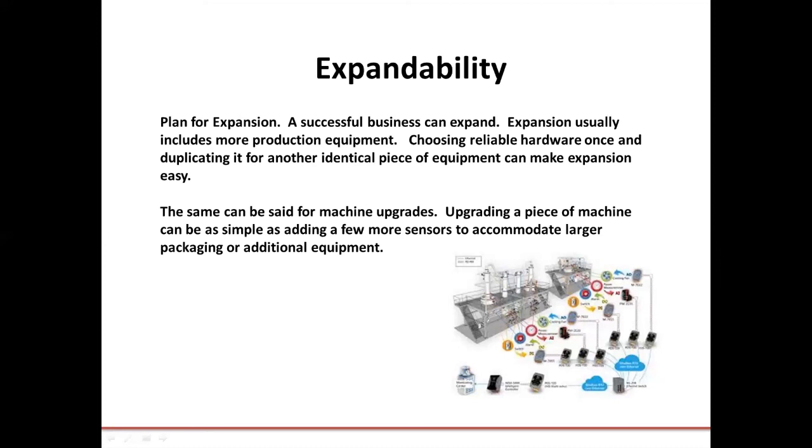It's also very economical, because if you plan for expansion, you don't need to purchase something later that can do more. For instance, our Easy Datalogger software is expandable up to 1024 tags. If you get past that, you can run another instance of Easy Datalogger, but you would not be able to combine them. So in that case, something like InduSoft, which is a full-blown SCADA package with the ability to upgrade the number of tags, would be a more ideal solution if you plan to get that high or need that functionality.